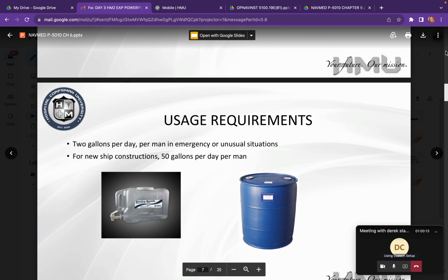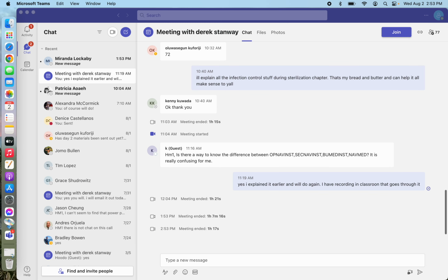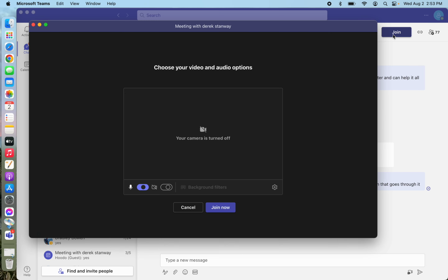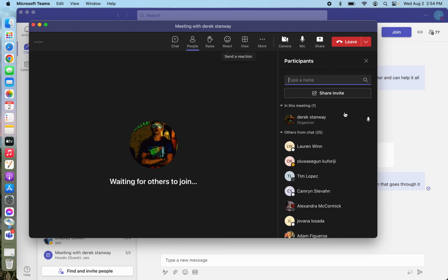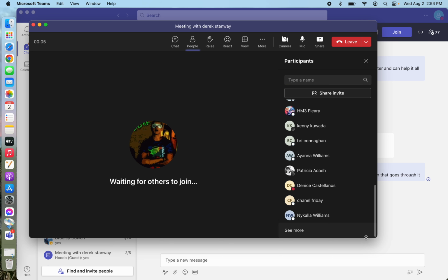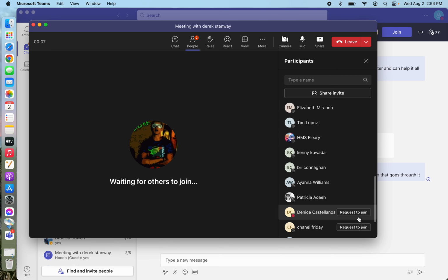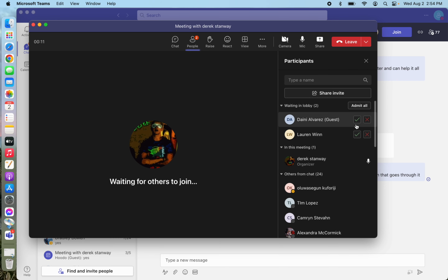All right. Receipt and transfer. Testing must be done prior to any hose connections. The MDR checks chlorine levels, FAC, free available chlorine, and notifies the engineering department if not up to par. If water taken aboard does not meet the standards, it must be held in storage, treated, and tested before being distributed through the system.